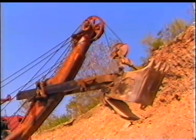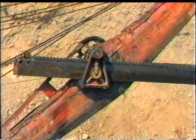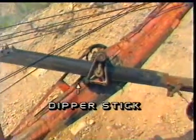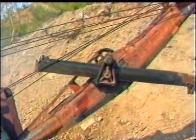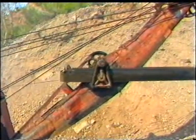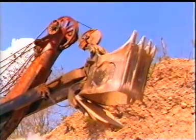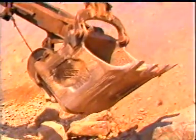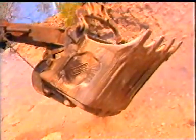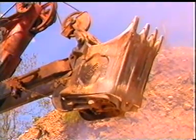The boom is a massive beam hinged to the deck at the boom foot, which extends diagonally upwards. The dipper stick slides back and forth through the saddle block attached to the beam. Its lower end carries the dipper. It's a steel box open at the top and closed at the bottom with a hinged door. Its cutting edge enables penetration into earth.